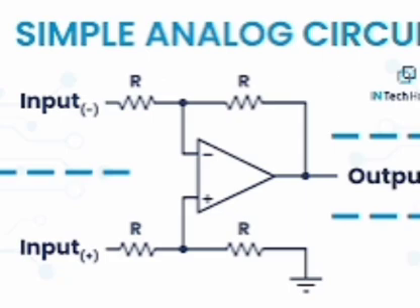Clamper: a circuit which can add DC voltage to an AC waveform. A clamper does not change shape of the waveform, it only shifts the waveform up or down. Application: a clamper is used to reinsert or restore DC component into a waveform which has lost DC component after passing through a processing circuit such as amplifier. Clamper is also called DC reinserter or DC restorer. Clamper means two types: negative clamper, positive clamper. Negative clamper lo add negative DC, positive clamper lo add positive DC.